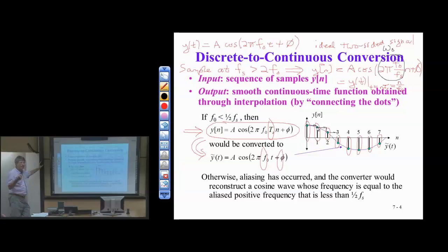Well, the thing is, if the original signal in continuous time were a staircase function, it would have incredible harmonics at the very high frequencies. So if I sampled at only just above twice the fundamental frequency of that, which is 1 over the fundamental period, I would filter out all those harmonics and I'd get back a sine wave. So there's a trick there in how you can convert a square wave into a sine wave.